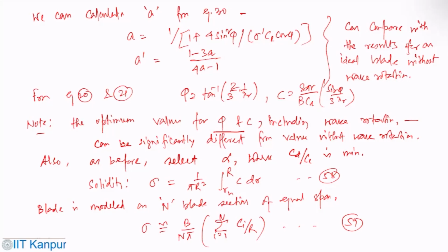Now, blade shapes, or sample optimum shapes, for different conditions could be obtained, assuming different lambda values, different B values, and that includes the wake rotation. That's how you can use these parameters to find out those things. But one has to consider that they would show different kinds of variation.